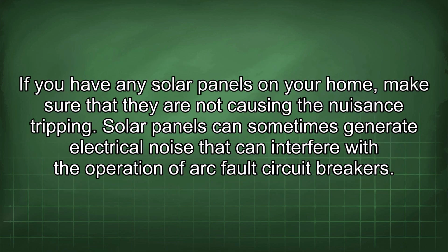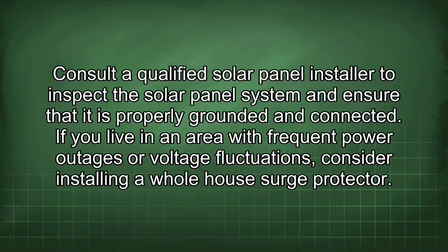If you have any solar panels on your home, make sure that they are not causing the nuisance tripping. Solar panels can sometimes generate electrical noise that can interfere with the operation of arc fault circuit breakers. Consult a qualified solar panel installer to inspect the solar panel system and ensure that it is properly grounded and connected.